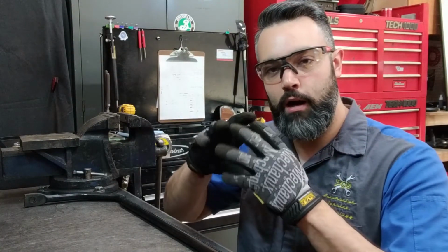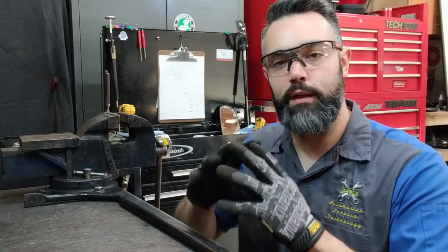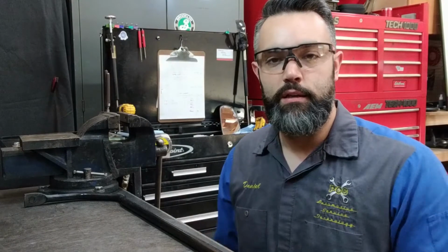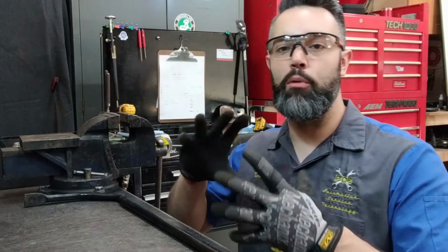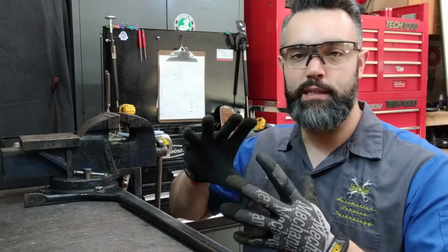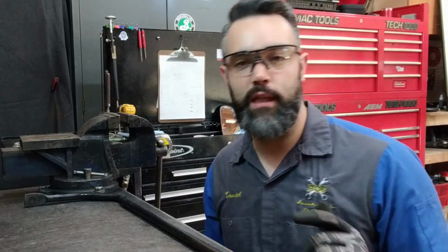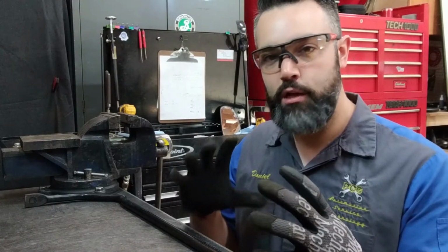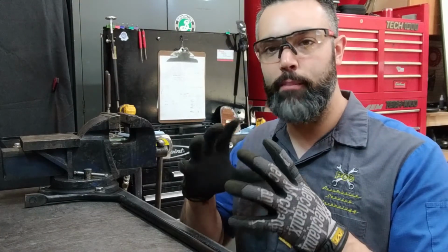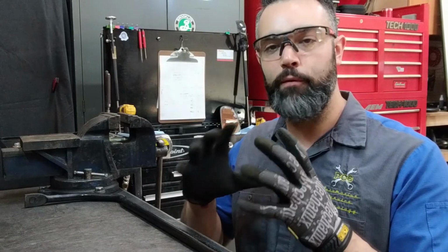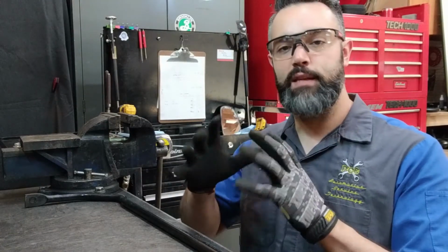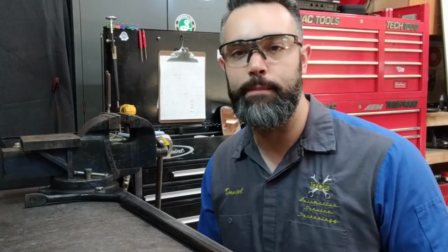So this sway bar is actually operating at peak torque of the electric motor as the deflection is occurring. If the driver sets a comfort setting, it's going to resist less and allow more movement, but it's still going to provide some resistance. If a driver selects sport suspension, then the electric motor can use more amperage to resist smaller amounts of movement with more force. So this is actually going to change the stiffness actively depending on driver input.